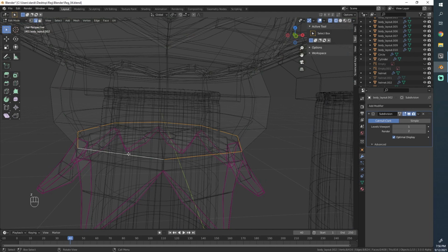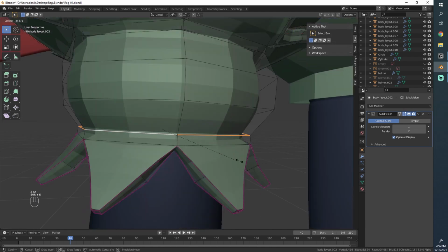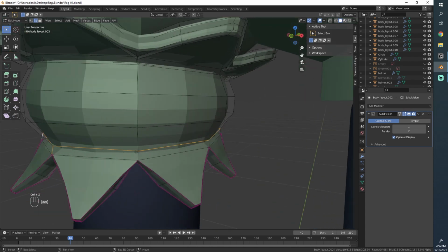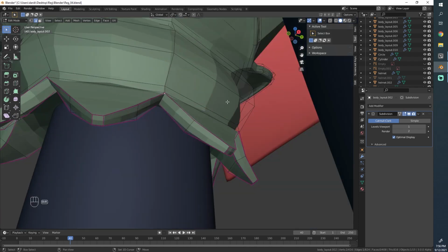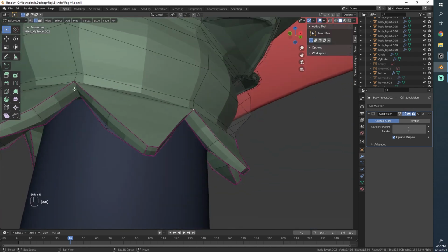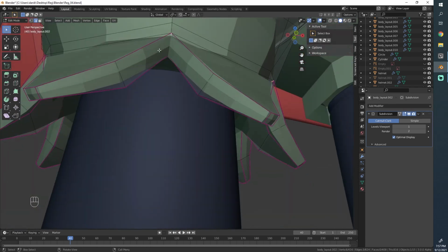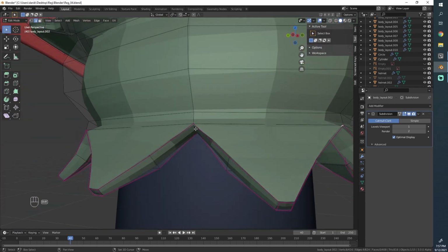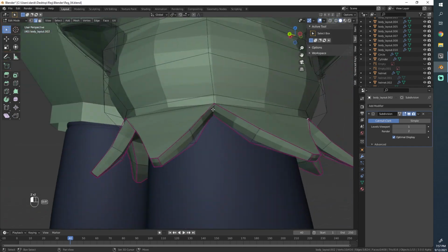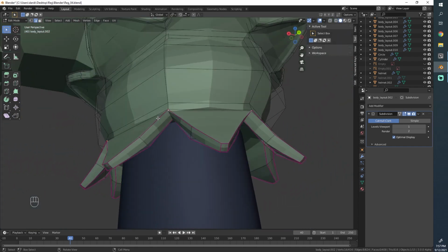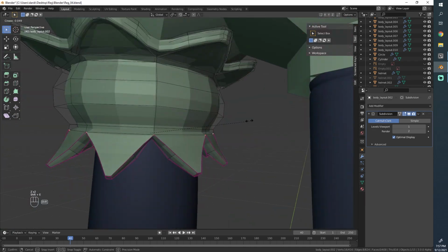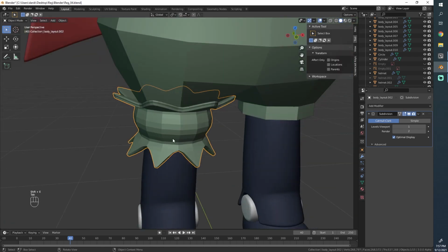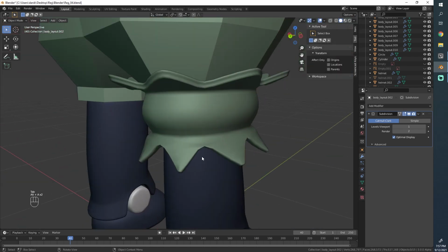I'm also going to maybe crease this ring here, and maybe we should just add this as well, because I don't think it... actually, what happens if I don't do this? Yeah, you know what? I think we should have left this as it was. Then we'll get a nicer, rounder shape all around. So Shift E, reduce the creasing here, and that looks already a lot better.